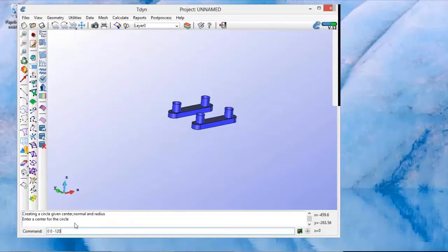As you can see, all the model and all the domain is centered in the origin, but the bottom of the domain, we will explain later how this works, is going to coincide with the depth of the domain we are analyzing. So in this case it is minus 120 meters.